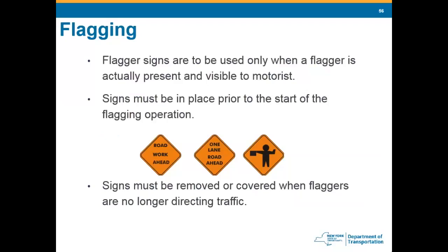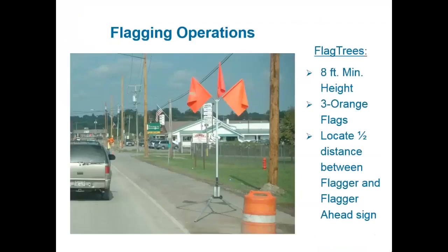You know, you gotta keep it real time. You've gotta keep it consistent. Again, these are the signs that we're going to use for that. Flag trees, minimum 8 feet, 3 red flags, halfway between the flagger and the work.